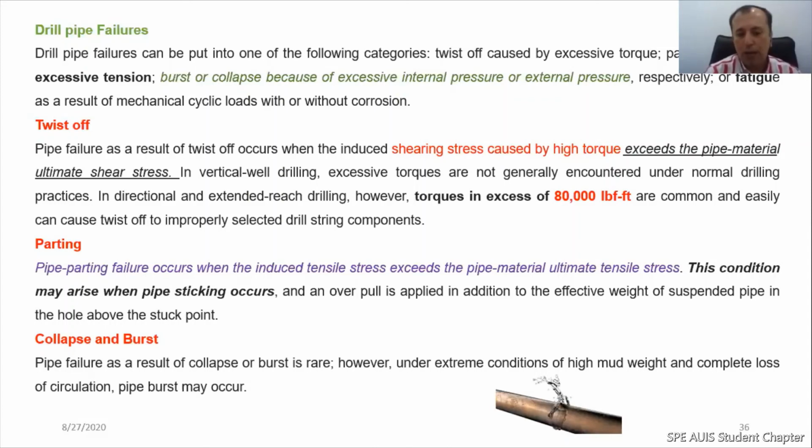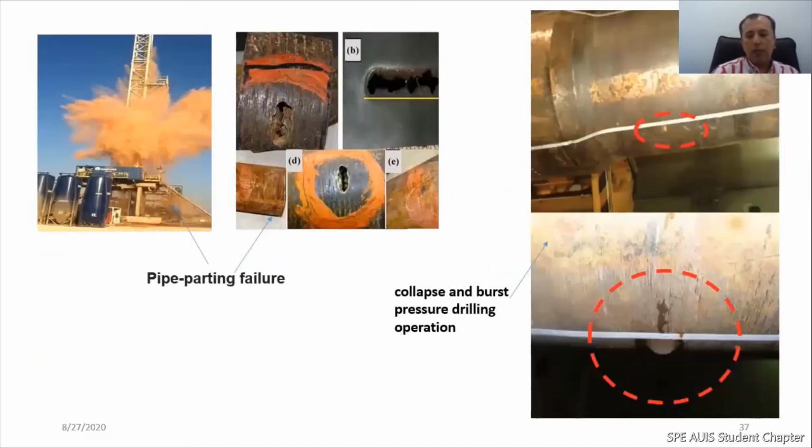Pipe will fail. The pipe that we are going to send the water, drilling mud or cement slurry down will fail. Here are some pictures of pipes when they failed. Take a look at how it looks when it fails and you are applying about 1000 psi. Look what damage you are going to see in the field because of that high pressure and sudden failure.